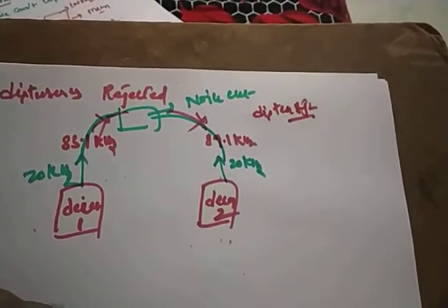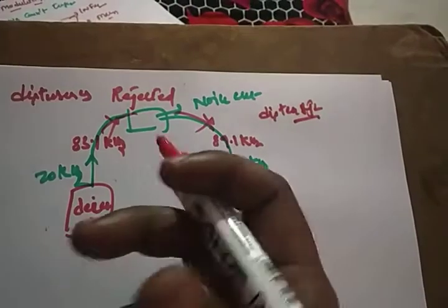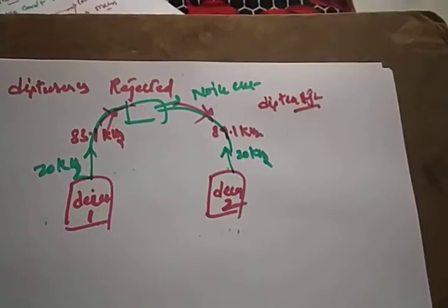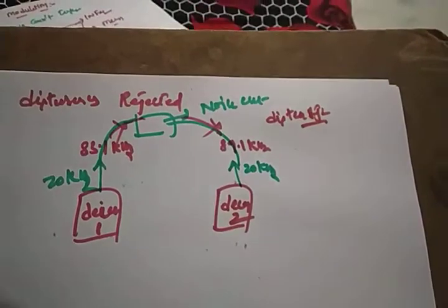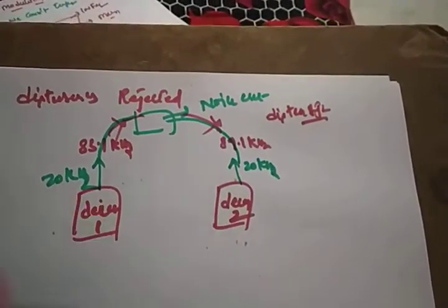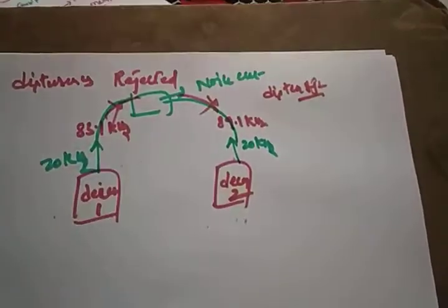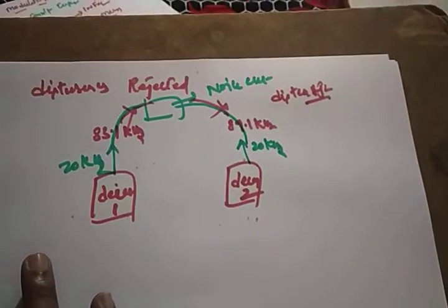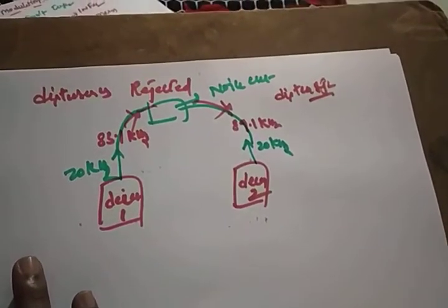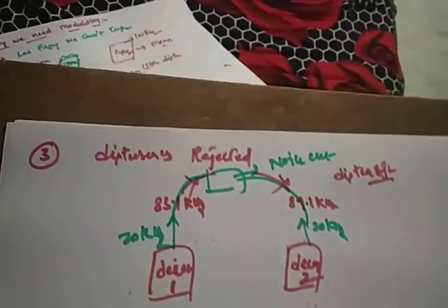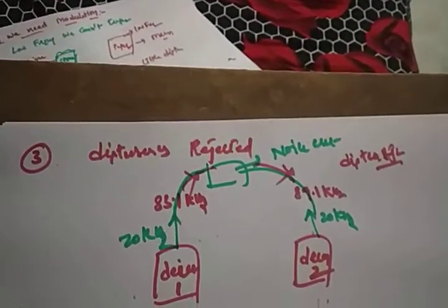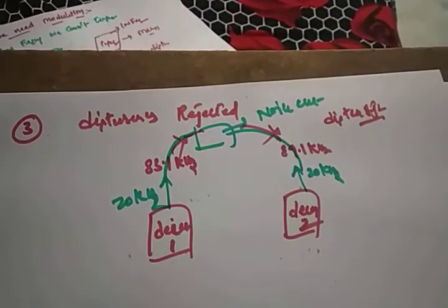Right? That means if you don't modulate the signal, definitely those two frequency signals will meet somewhere in the air. So definitely disturbances will occur. If you modulate, each and every device has some frequency that is substituted after the process of modulation, so these two different frequencies won't connect with each other. That means the disturbances will be rejected. So that's the third need of modulation.